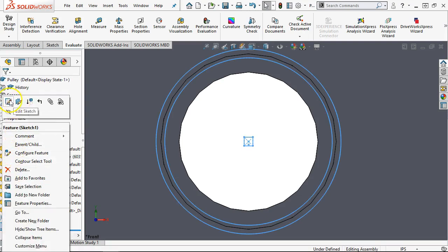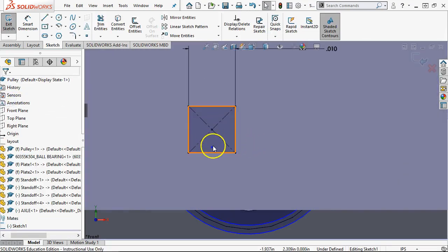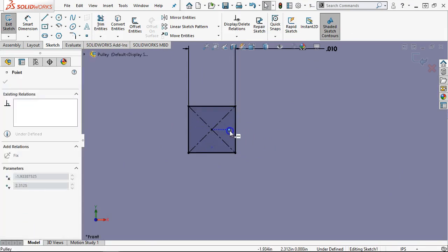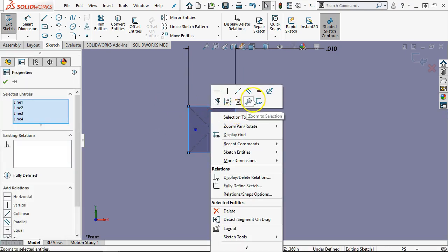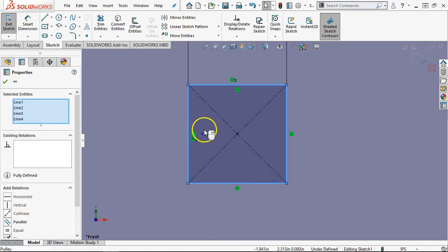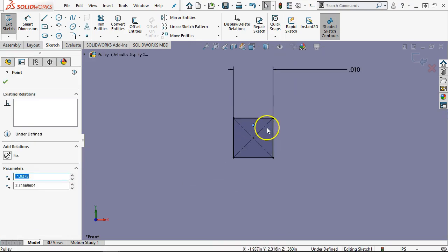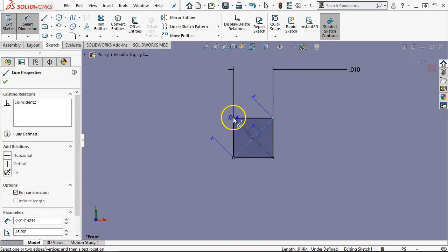Let's try that again. We'll edit the sketch so we can go left to right plus or minus 5,000ths, but we're going to have closer to about 7,000ths, maybe 7,500ths, that we can go on the diagonal. So we're not getting the same condition as if we treated this as a circular tolerance. And that's what the positional tolerance is going to do for us. All right, so that's one location, one position. Now let's see what that works out to.